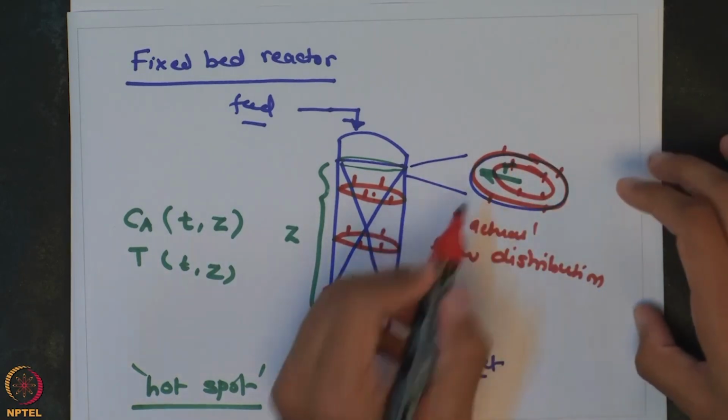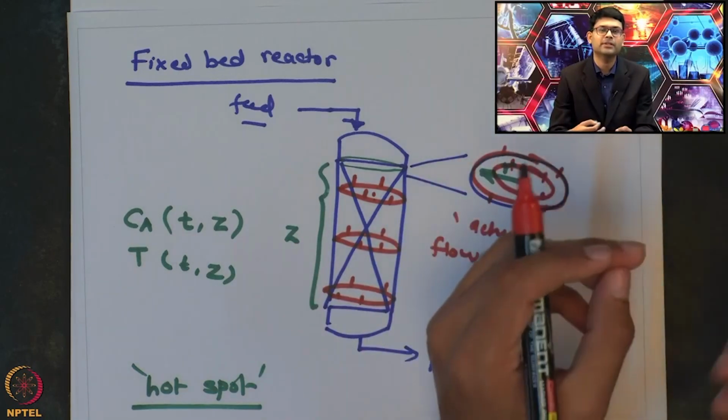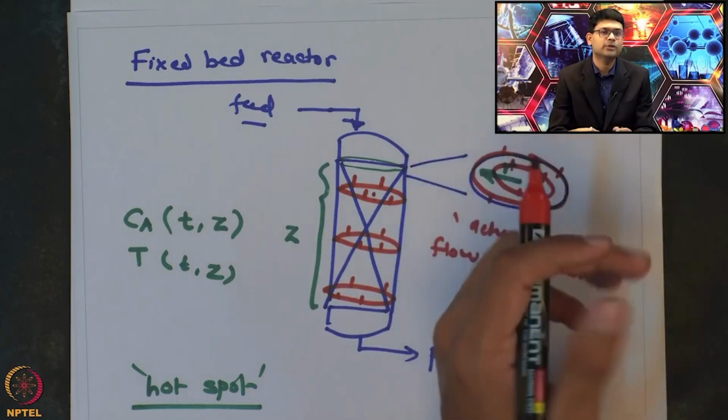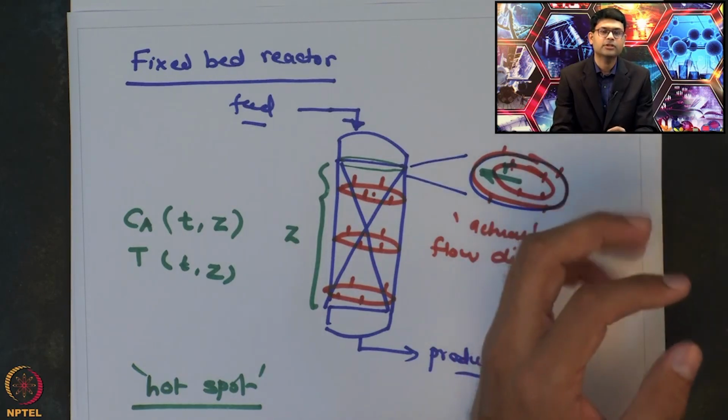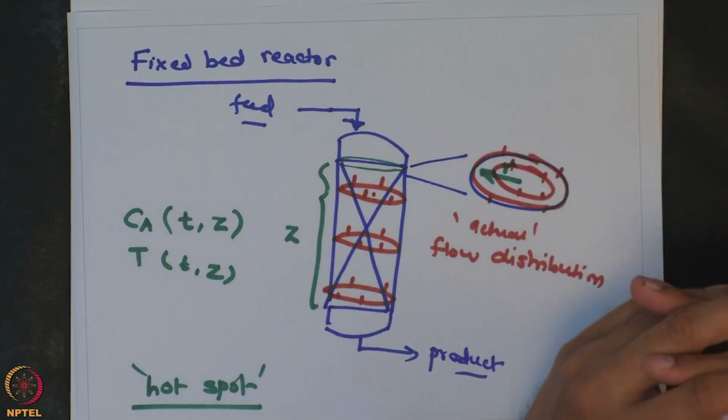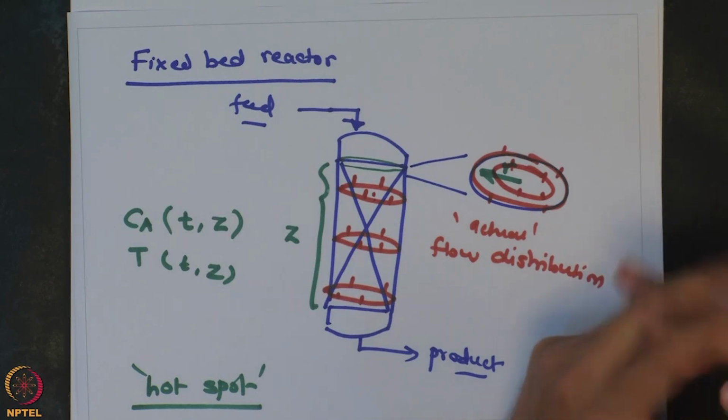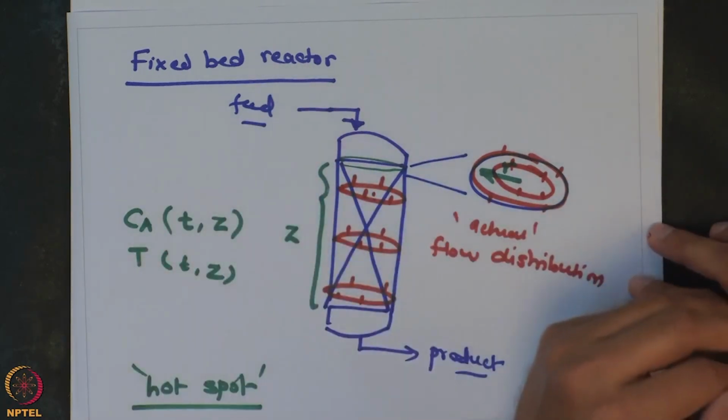So the idea is that you want to put in as many eyes into the process in terms of temperature measurement, so that you can capture if a hotspot is developing. Having all these 15 or 20 temperature sensors, you have many measurements. From that you want to identify where the hotspot is, and the hotspot would be the maximum temperature inside this reactor.